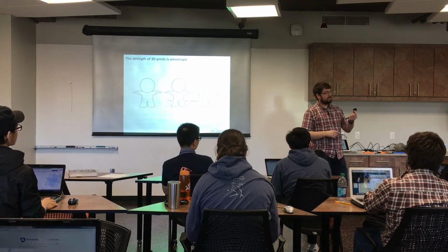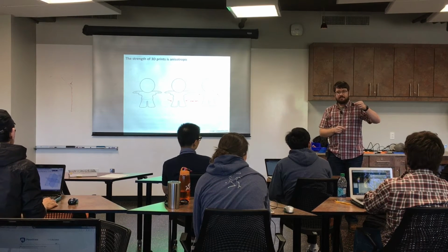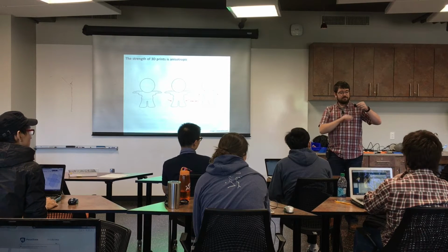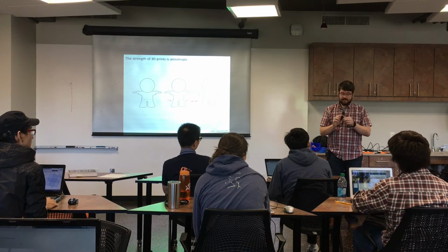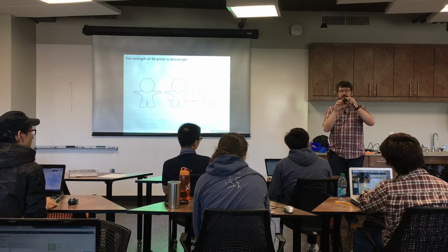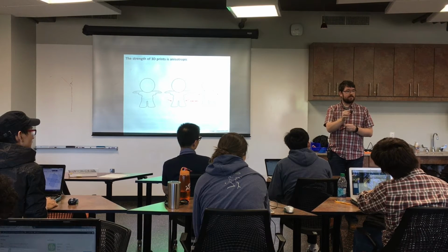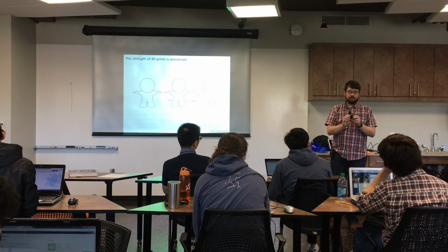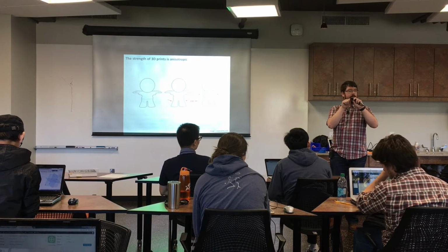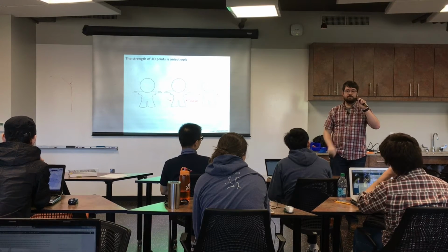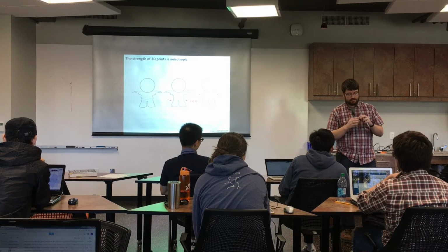This part is a little bracket for the lab, and actually I ended up printing it sitting like this on the printer because this was the plane that I cared about least. I wanted to have more strength in this direction. And this big hole produces overhangs that are over 45 degrees when you get towards the top of it. And so by printing it like this, I got around that problem completely. Another way you can do that is make the hole a little bit bigger and then put something flat across the top where you only have 45s there, and then it's just a small bridge across the top of the part. So I'll send that around too, but you can see how that works.